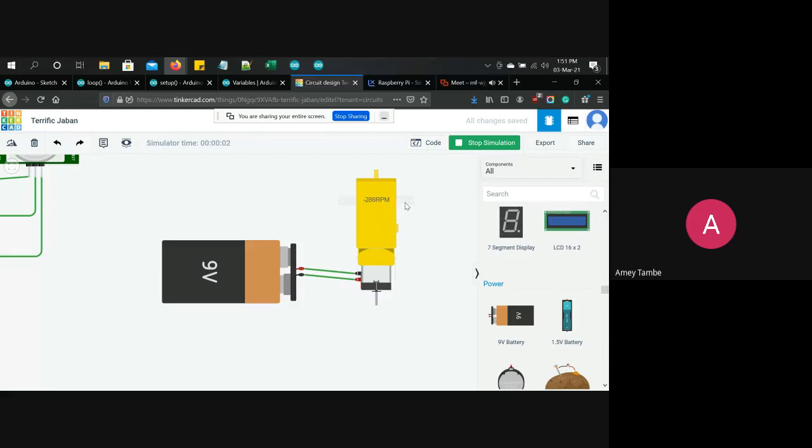Now you can see the shafts are moving towards me, towards the signal, and it is giving us a minus RPM. So it is a reverse direction, right? And now it is moving reversely, so it is a reverse direction. If you wanted to check the direction again on the simulation, then you need to see the readings over here. Like here it is showing minus 286 RPM. So it defines that you are having reverse rotation.